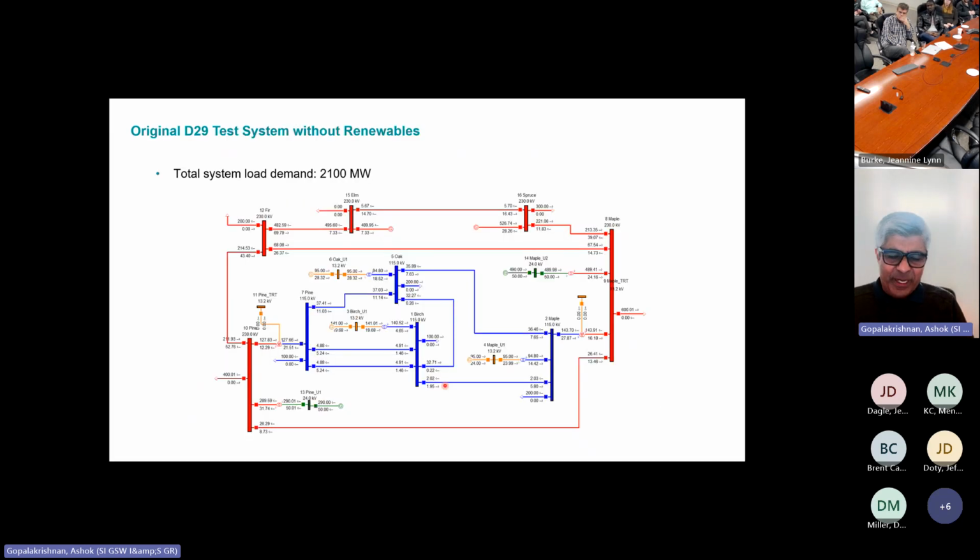Okay, so again, that was a quick capture of an event we studied a few years ago. And that module, combining the stability and the protection behavior, is very useful if you have to evaluate out-of-step relaying, the loss of field functionality, different protection functions that you normally would not evaluate under just a steady state condition, right? What the traditional analysis that protection engineers do. And with the renewable penetration and less inertia in the system, it just becomes more critical to be able to do these kinds of studies.